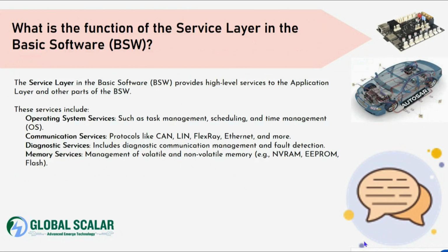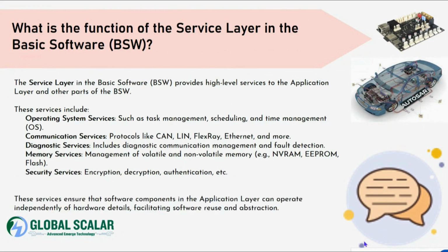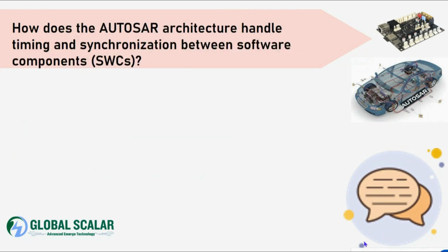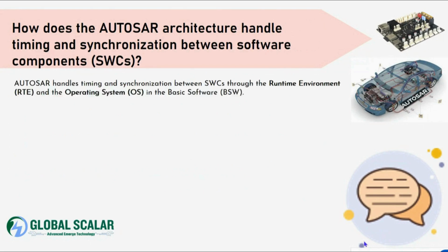Memory services are the management of volatile and non-volatile memories: NVRAM, EEPROM, and flash memories. Security services include encryption, decryption, and authentication. These services ensure that software components in the application layer can operate independently of the hardware details and facilitate software reuse and abstraction.